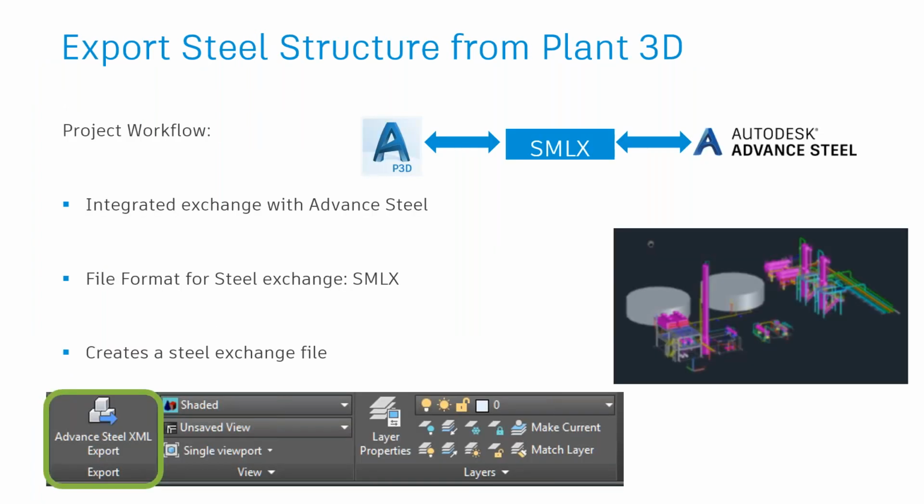Now let's talk about a bit of detailed examples, because when I talk about Autodesk solutions, when I talk about structures, where we use tools like Autodesk Advanced Steel and tools like Plant 3D, which could integrate between each other, where we utilize Plant for doing our equipment, piping, and plant layouts, whereas the structural piece of information could be handled very well inside Advanced Steel. Now, the beauty is these two tools can integrate via a different interoperability format like steel markup language or an XML format, which is there.